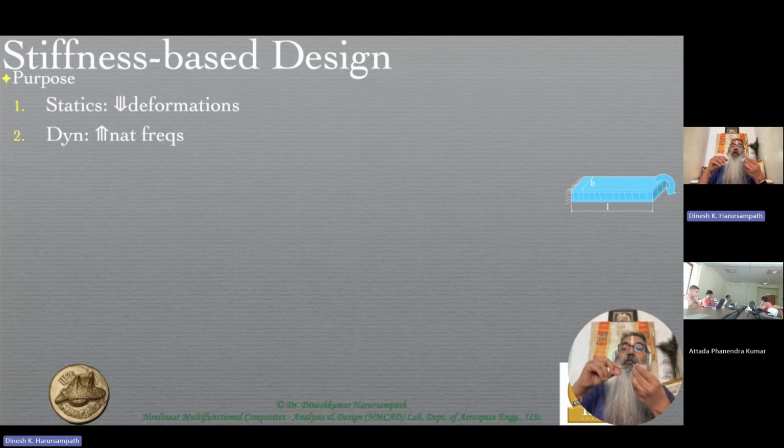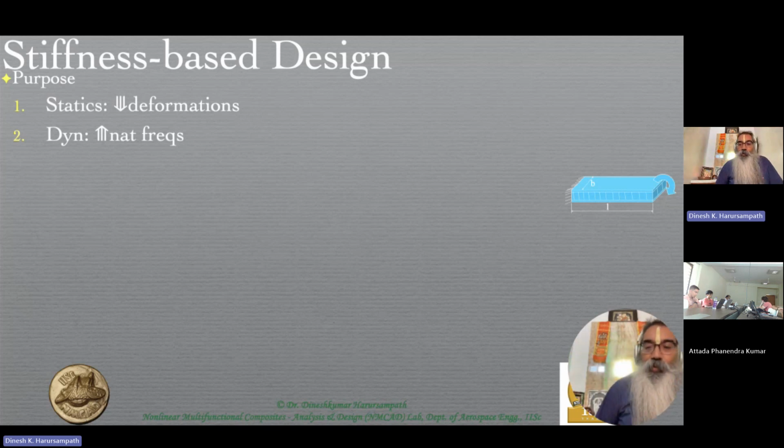In other words, in the helicopter, if I'm increasing towards my right, I'm increasing my pitch. Then only when the rotor blade comes to the forward, the flap will become maximum. So in this case, on my right side, I'm increasing the pitch. Then when I go forward, the flap will become more.